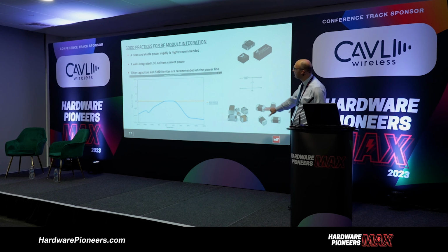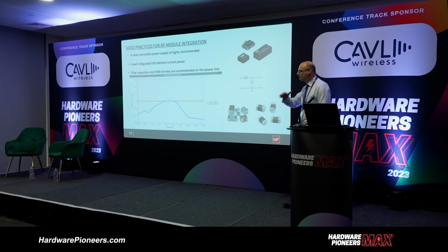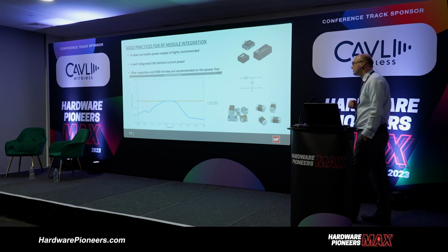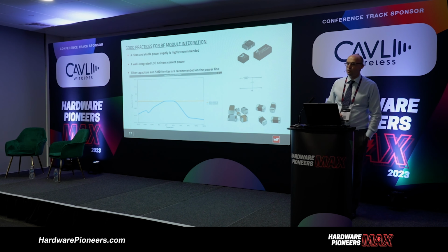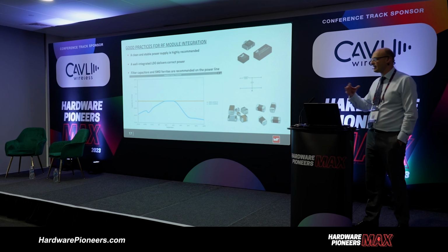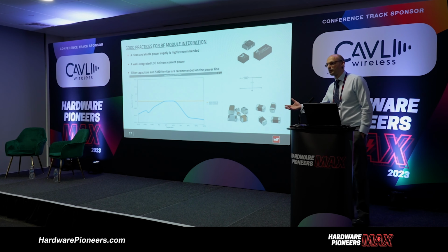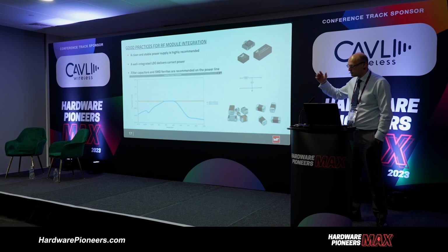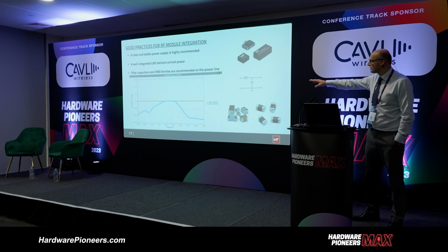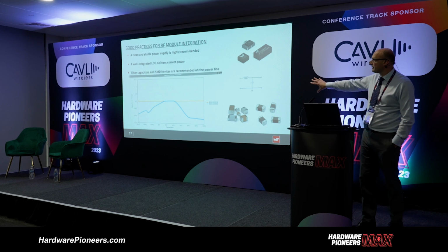So all we're trying to highlight here is the variance between MP0, which is the yellow line here, which, because it's a class 1 material, there is no effect with regard to temperature, versus an X7R that will vary in capacitance value with regard to temperature. So once again, this can have an impact, not necessarily from a conformity perspective, but in a real world application. You might find that a customer starts complaining of potential issues, maybe due to higher or lower temperature, and that's because, once again, the capacitance value is varying. You've based all your calculations around a certain capacitance value, and that can cause problems.